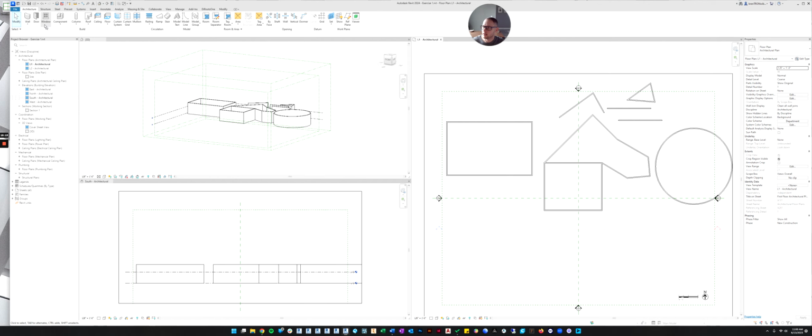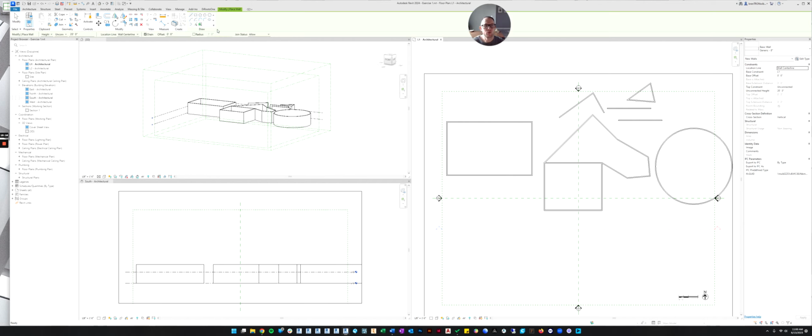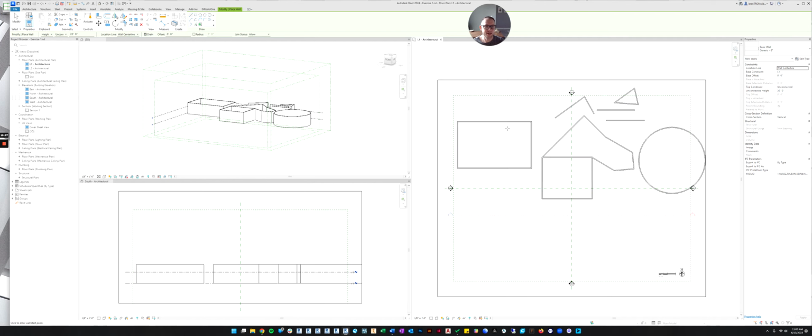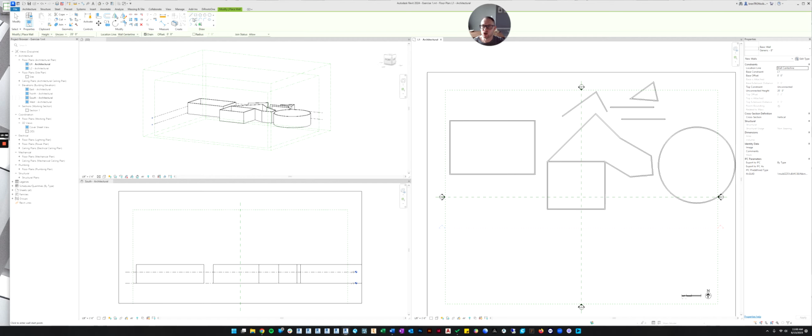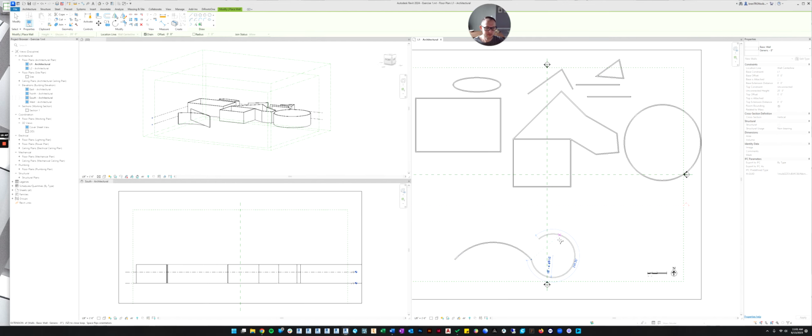All right, let's go back to the wall command. The reason we're taking so much time on the walls is because a lot of these things that we're learning in the wall command translate to other commands. You'll find some similarities. So we won't take this long for each command, but it's good for you to practice. And you can play with the different drawing styles. Like you can also do an ellipse, which is like a circle that's not the same dimension on all sides. You can do an arc, where you pick the two ends and then you pick the radius. You can do a polygon.